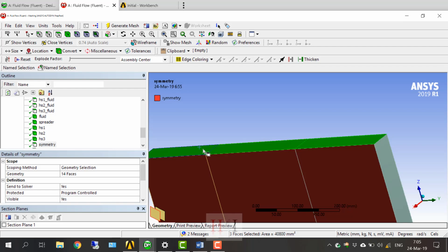Because as we can remember from the Bernoulli equation, we have P plus rho G H. This is the energy of the flow. If you calculated this for here and here, you will find that this value here is bigger. So the flow goes from the higher value to the lower value. So it comes from up to down, which is not a natural phenomenon. So you have to define a variable pressure.